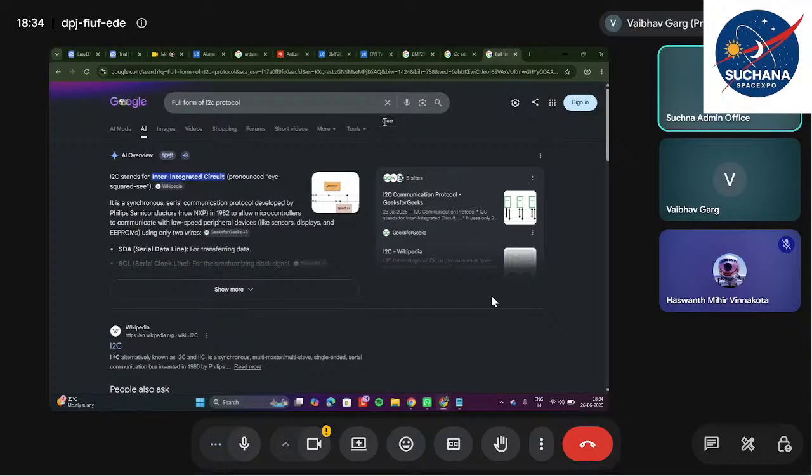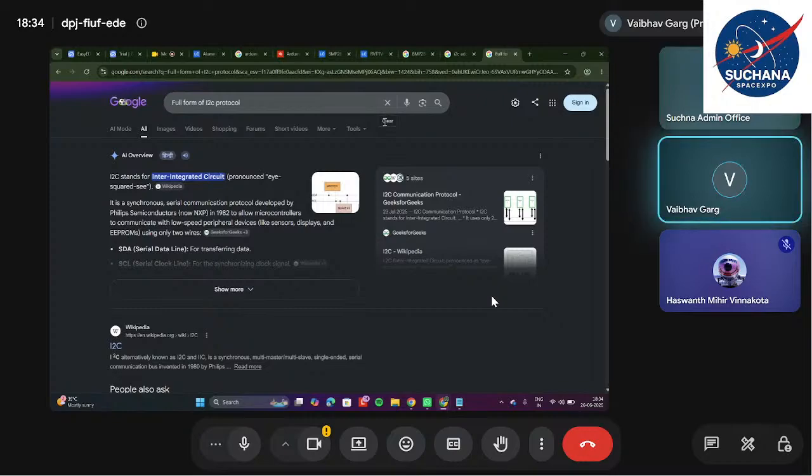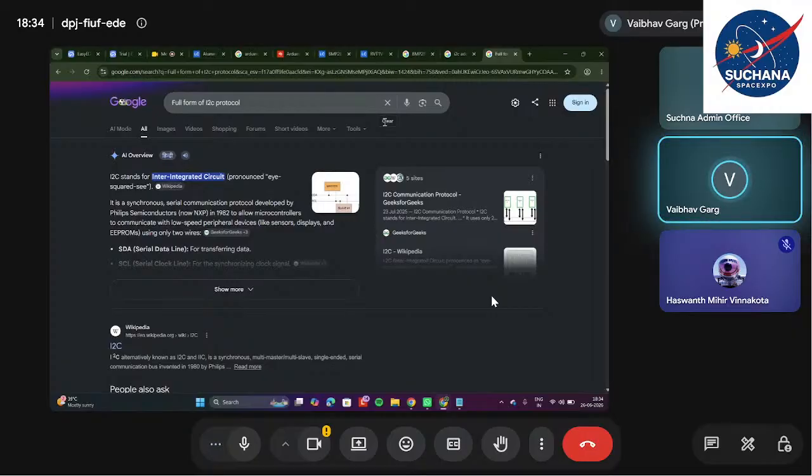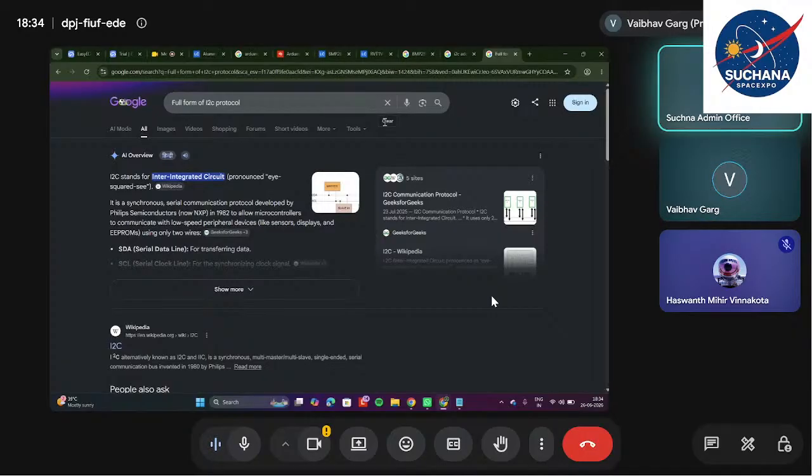or sensor B. Okay. So now what do you think the reason could be that the engineer who designed that BMP280 PCB had put two different I2C addresses? Earlier I told that every PCB will have a unique I2C address. But sometimes a few PCBs may have multiple I2C addresses. So now this BMP280 is having how many I2C addresses? Two. Yeah, 0x76 and 0x77.